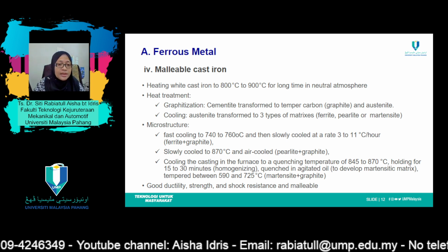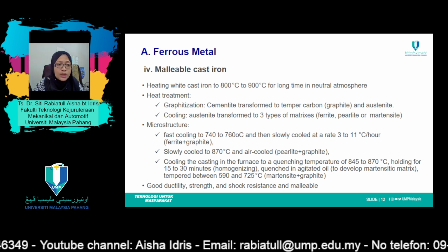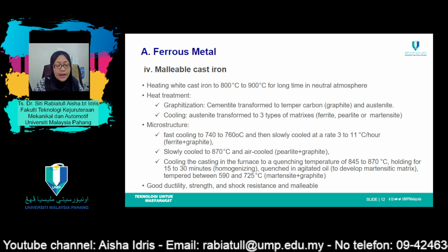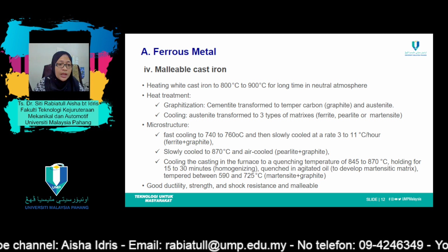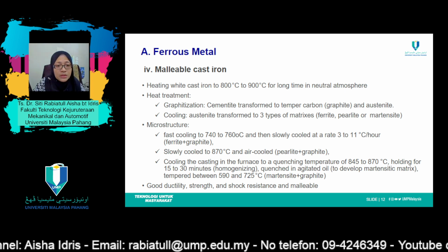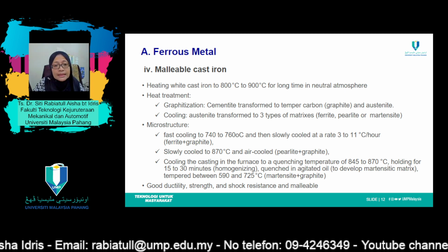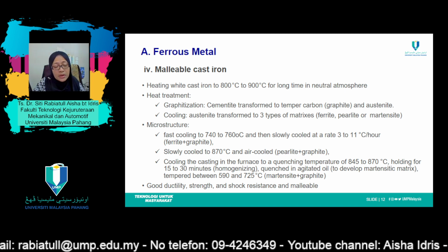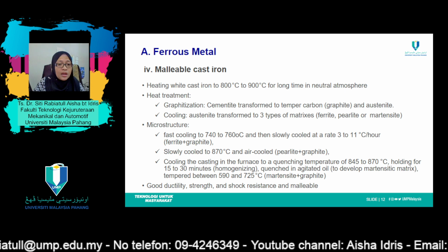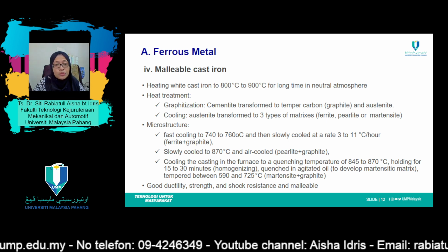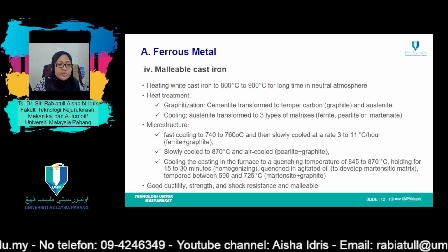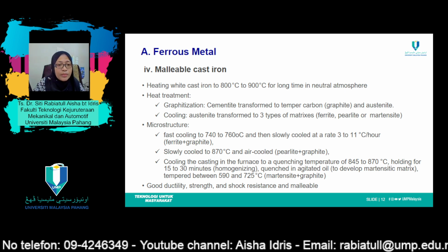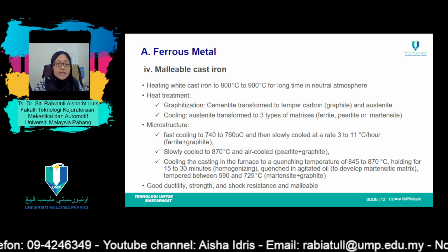The microstructure is similar to that of nodular iron, which accounts for relatively high strength and appreciable ductility or malleability. Representative applications include connecting rods, transmission gears, different cases for the automotive industry, and also flanges, pipe fittings, valves, marine, and other heavy-duty services.